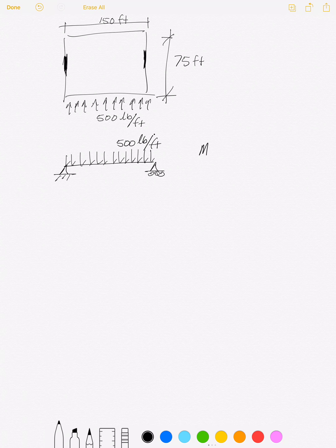And so then let's find out the moment. Remember from class there's several ways to do this. We can cut the beam at the center, eliminate the right side, take a look, and determine what the moment is by the cuts. We can draw the bending moment diagram, or we can use an equation that we derived last semester and some of you may start to remember. On your exam, I think I put this on one of the equation sheets, so you'll have it.